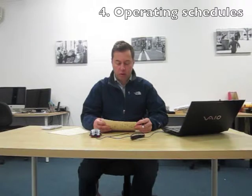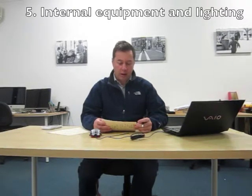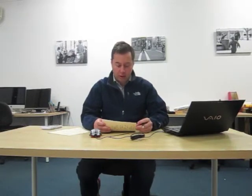In addition, we added the occupancy numbers and the number of people within the building, the operating schedules, and equipment that consumed lighting and power. And that was important because lighting and power equipment emit heat and increase the building's internal heat gain.